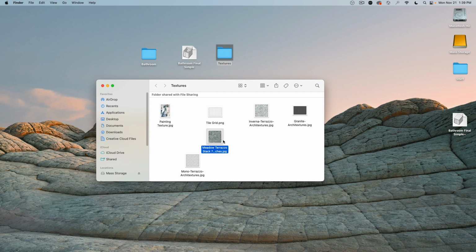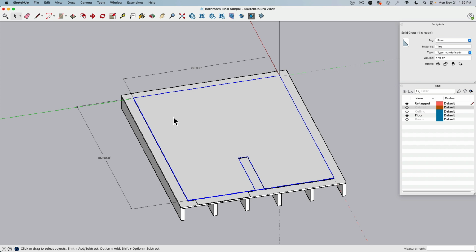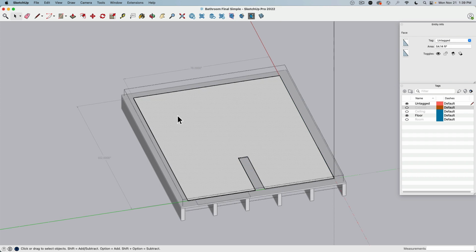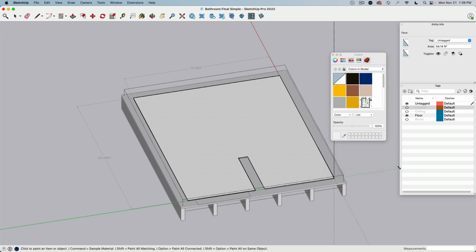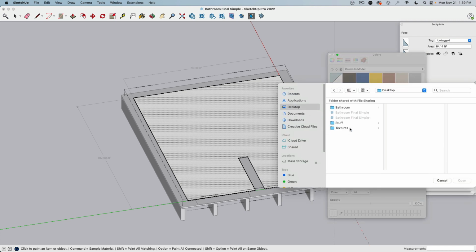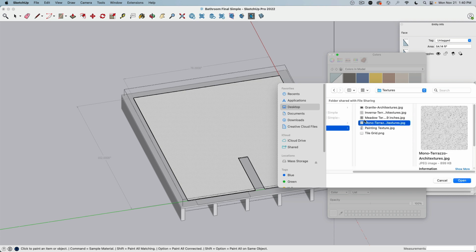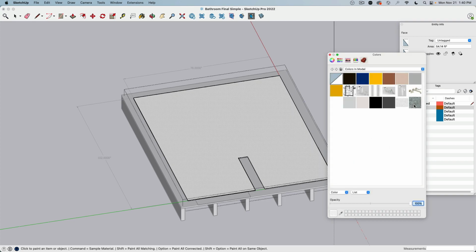so what I can do now is when I go to SketchUp, I select the group, double click, select the top face, and now I can create a material. So I bring actually this tile in. New texture. I will navigate to where the texture is. And there I have it. Now I can specify now, so this should be 78 by 78. So I'm stretching this a little bit. Very good. It's fine. There.